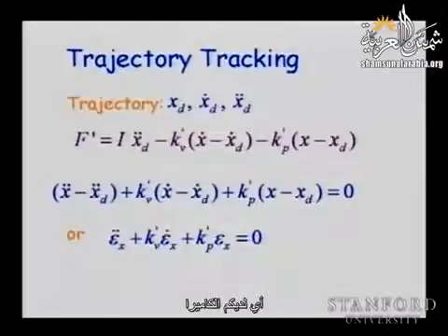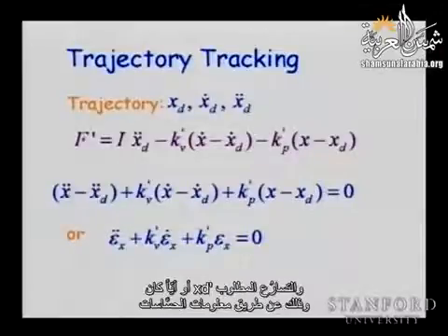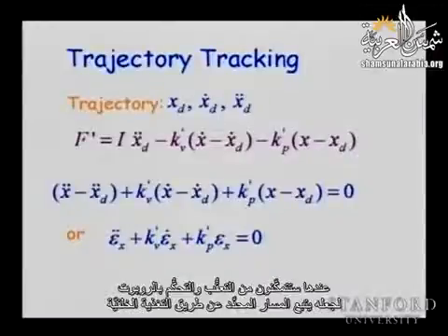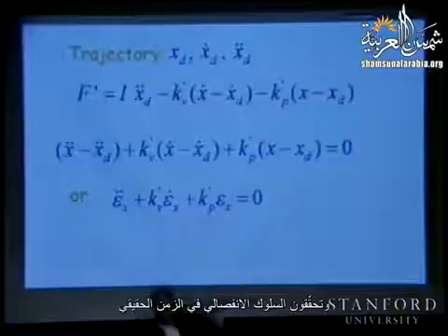That is, you have your camera, you are doing visual servoing, you get your x desired in real time, x dot desired, acceleration, whatever, from your sensory information, and you are able to track and control your robot to follow the trajectory specified by your feedback, and in real time you are achieving this decoupled behavior.